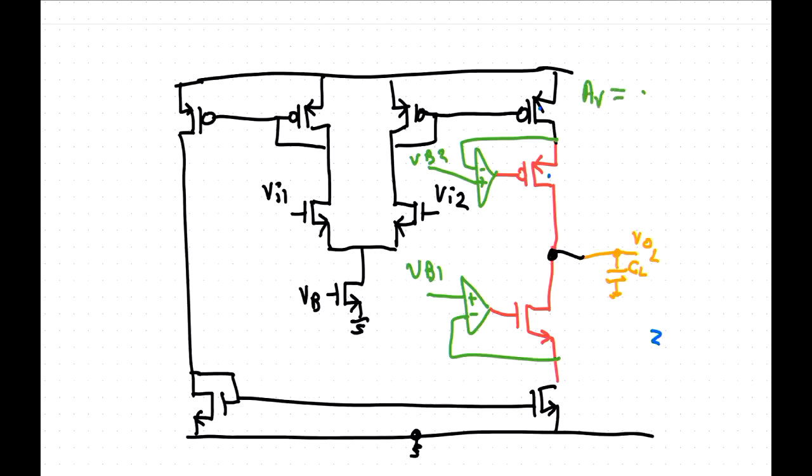So now we get a gain which is going to be GM times RDS, GM RDS. That's from the cascode structure here. But then we're going to multiply that also by the gain of this amplifier, like that, times probably 1 plus A. And A is probably going to be GM RDS. We want to have a simple amplifier. So that one there is probably in the order of GM RDS.